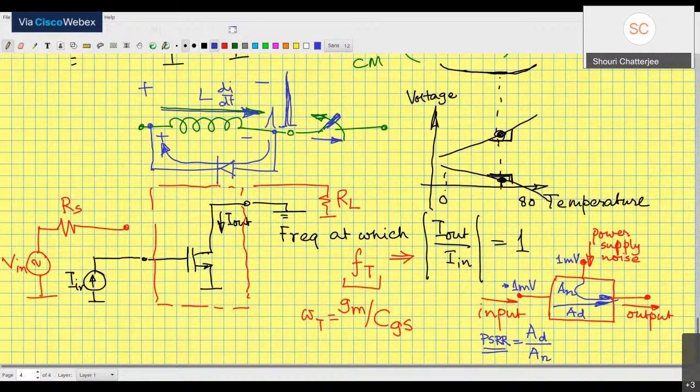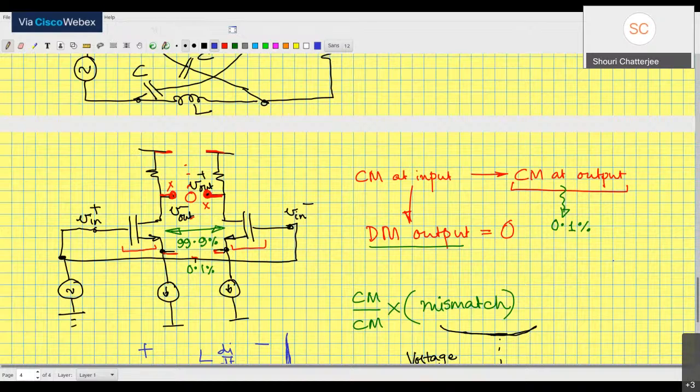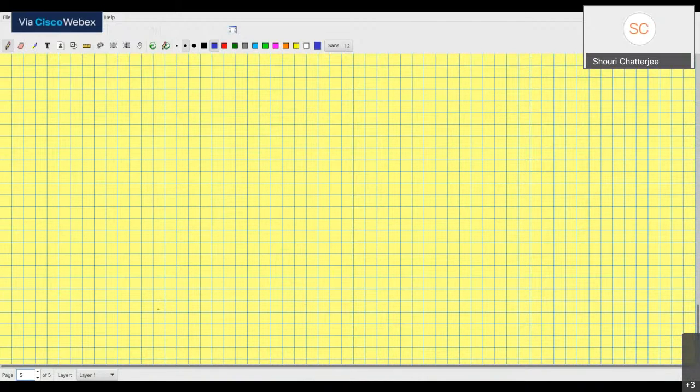Need of the current source at source terminal in diff amp circuit. What is the need of the current source at the source terminal of the diff amp circuit? Over here, why should I put a current source over here? And the reason why you put it over here is as follows. You put it over there because you want differential gain but no common mode gain. Okay, again, similar to the story with the power supply rejection, you want to reject the common mode also.